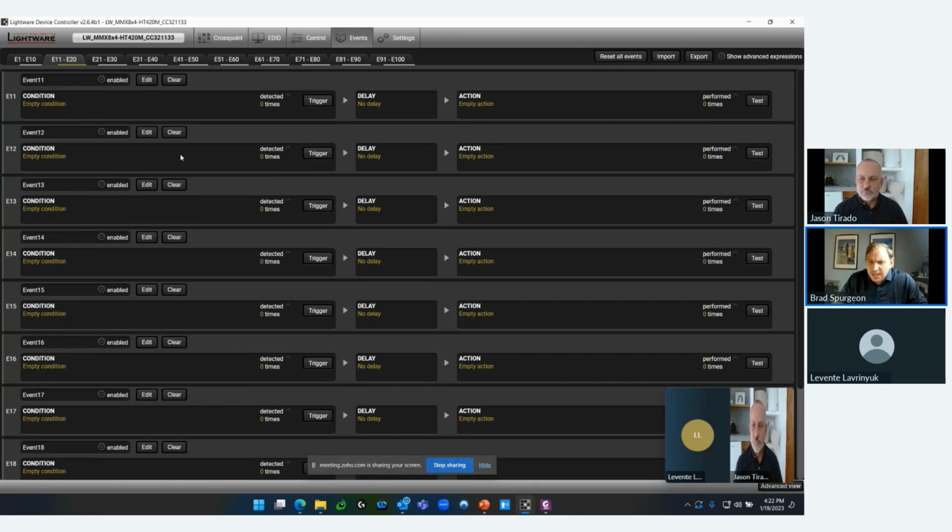Traditionally, that was a little bit more of a complex operation than it ever had to be. You usually had to have a control system that constantly polled the status of a device, and when that status changed, then it performed an action. Like, it was constantly looking for somebody to connect something. So you'd have a control processor in your server room constantly looking at all these endpoints, or even buying a control processor per room. That's all it did.